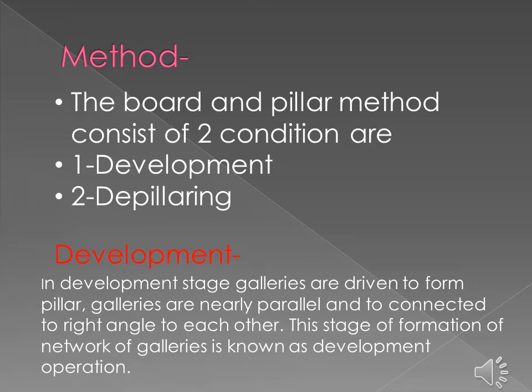Development is the extraction preparation phase which we plan in the mine plan. In the development stage, galleries are driven to form pillars. The galleries are nearly parallel and connected at right angles to each other. This stage of formation of a network of galleries is known as development operation.